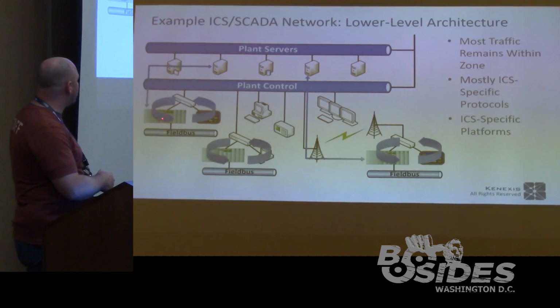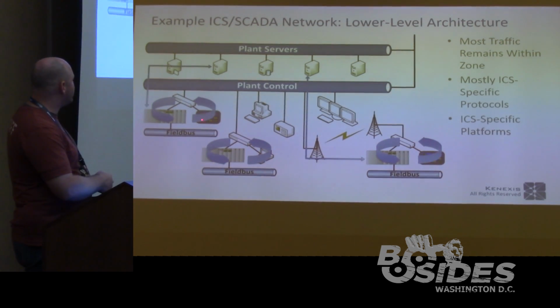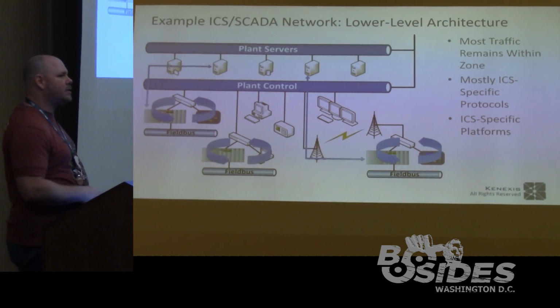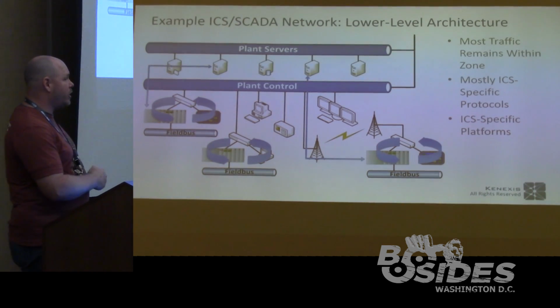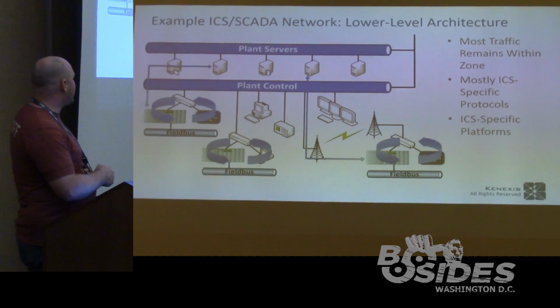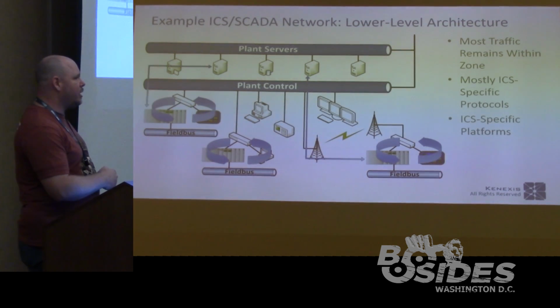So this controller is going to talk to some devices here on this field bus, and it's going to talk to this little HMI server, a human machine interface, and maybe that's a PC, or maybe it's some form of specialized panel PC or things like that. But almost all of that communication resides inside this switch and never leaves that switch. And a lot of times these are layer 2 switches as well, so you're not talking about really smart kind of devices.